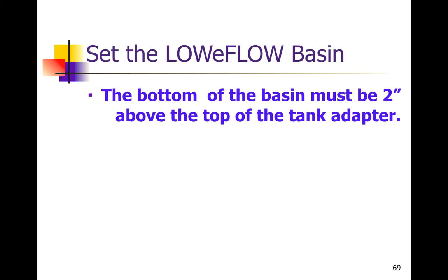Now, once we have the 2-inch plumbing for the tanks completed, and the interior parts of the tank done as well, we want to dig our excavation for the low flow basin. And it is critical here that the bottom of the basin must be at least 2 inches above the top of the tank adapter for the recirc tank.